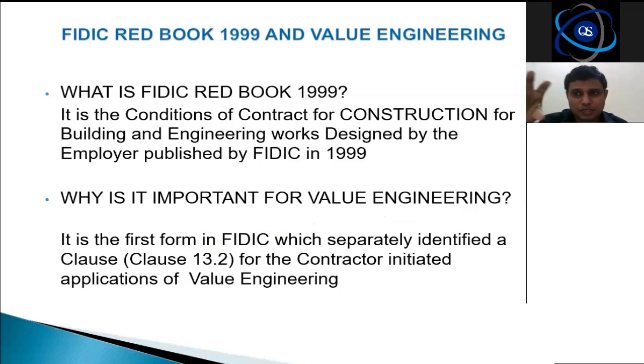But they recovered all the anomalies that were there, and in the opening phrase of the FIDIC 1987 version they stated clearly that a variation has to be issued under three circumstances. Number one, it has to be necessary. Number two, it has to be appropriate. Either necessary or appropriate. Number three, it should not vitiate or invalidate the contract. Right? I think you have gained very good knowledge about this.